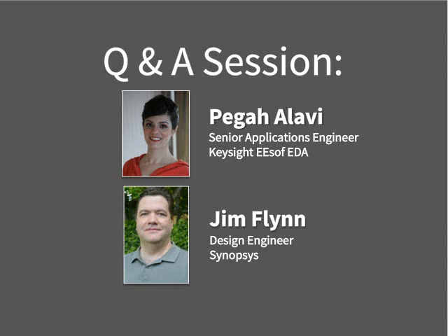I want to add a short comment, Bill, if I may. As Jim mentioned, there's various ways of modeling this. If you have a power-aware IBIS model, ADS is capable of running that simulation. A lot of times, as Jim mentioned, what you end up getting is that you'd actually represent that as receiver noise, and ADS can also handle that and simulate that correctly.